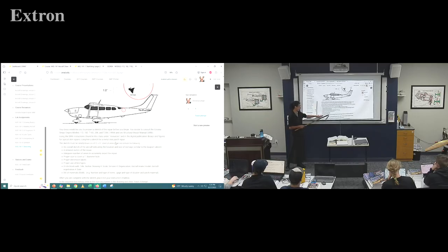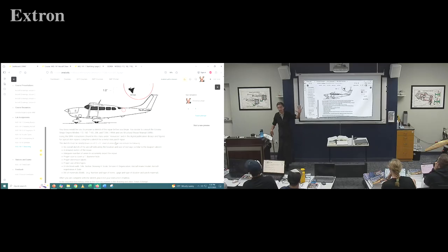to make sure you have the title, the author, the drawing number, this could be drawing 2, since we did 1 yesterday. On the scale, we're going to do a 1-to-1 scale, so full scale. Version, number 1 version of this drawing. Organization, SMAT. Aircraft make and model, that's Cessna 206, which it says up top. Aircraft registration number, I'm going to let you make up your own number. It has to be an N number since they're registered in the United States, so it starts with the letter N, and then 5 letters or numbers.